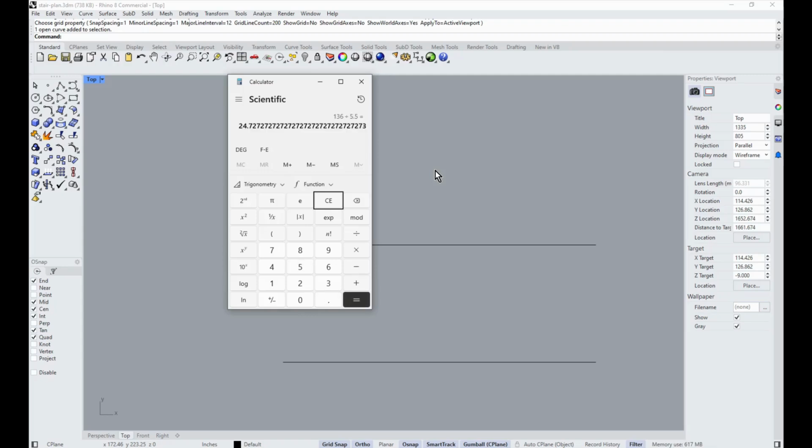So you get 24.72. Now the trick is this needs to be an integer. The number of steps has to be a precise amount. And there's a variance of 1/4 inch or less that they want each tread to be equal to the previous tread. A lot of people try to wing this stuff on the fly. They burn a lot of materials.